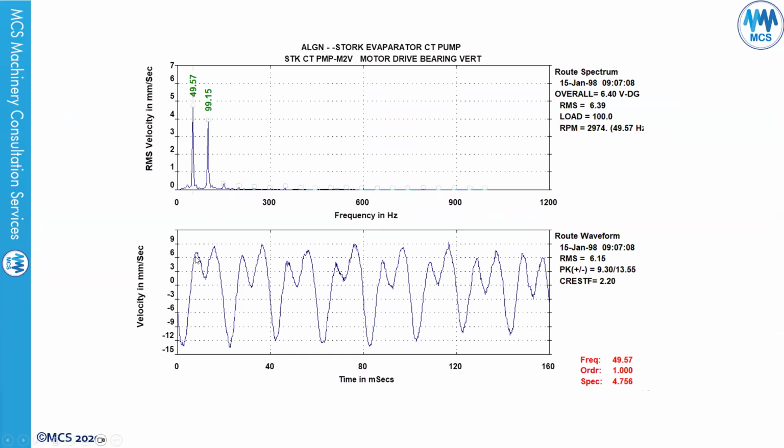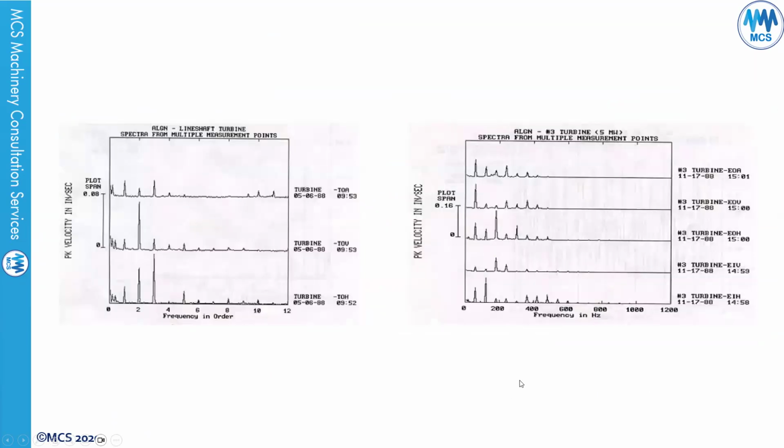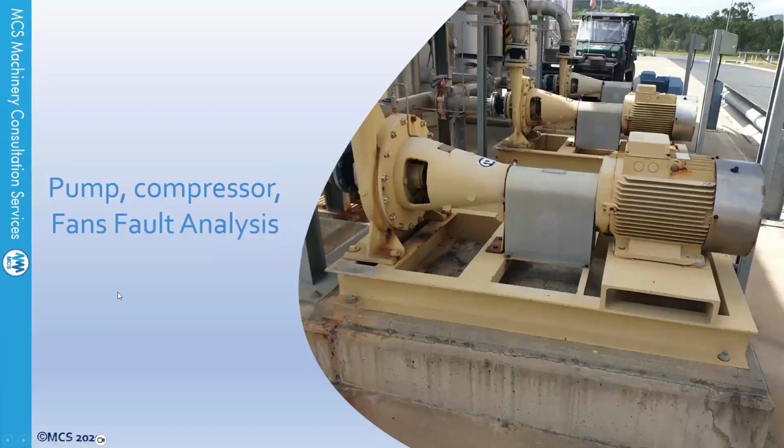You will see 1x and 2x, and also you will see a W, or we call it an M shape. This is the M shape on the vibration time waveform, or time domain. You can see 1x, 2x, and 1x, 2x, 3x patterns. These are all the patterns of how misalignment can look.